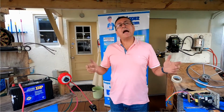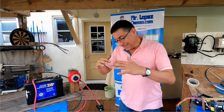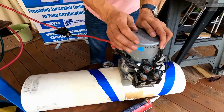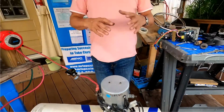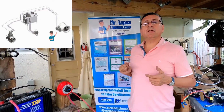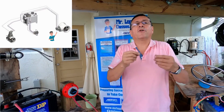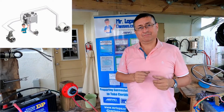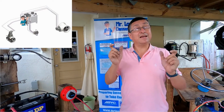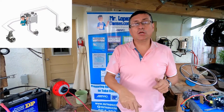It's not complicated. And now we are going to talk about the other type of bow thruster. The element is exactly the same. The only difference is that instead of an electric motor, you have a hydraulic motor, exactly like this. That hydraulic motor receives the power, the hydraulic power, from the central hydraulic unit. In the central hydraulic unit, there are a couple of solenoids, the servo solenoids, you remember, for right side or left side to control this bow thruster.